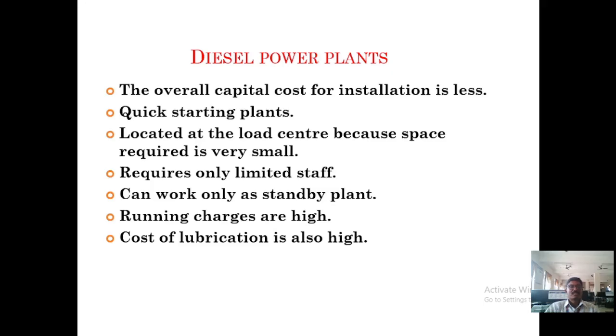The next one is the diesel power plant. Another source is diesel. The overall capital cost for installation is very low, quick starting is possible, and it can be located at the load center because the space required is very small. It requires only limited staff. It can work only as a standby power plant due to the running cost. Running charges are very high. The cost of lubrication is also high.